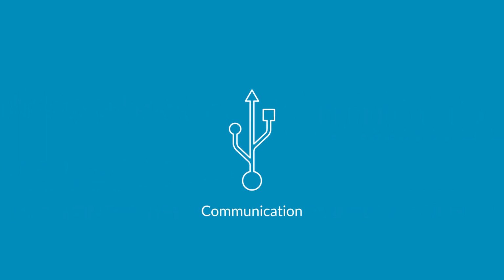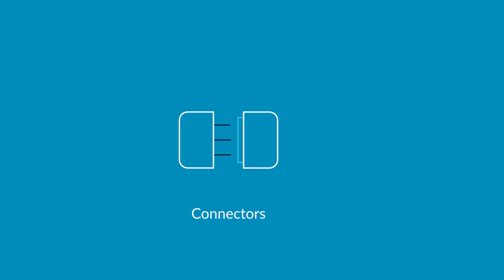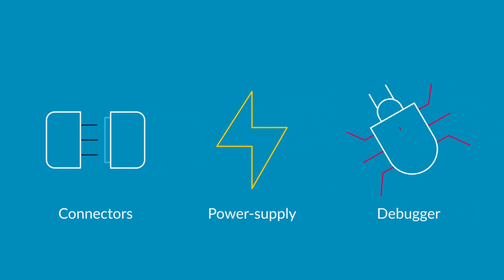For communication, there is a USB on-the-go with micro AB connector. There are Arduino Uno V3 and PMOD expansion connectors available on the board too. The board provides flexible power supply options, such as the ST-Link USB V-Bus or external sources. And there is an onboard ST-Link debugger/programmer with USB re-enumeration capability with mass storage, virtual COM port and debug port.